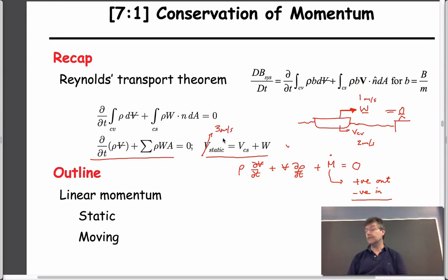So that was the basic tenet. The two important expressions are this mass conservation equation, which is the first thing we wrote just then. Increases in volume are positive, so if the volume gets larger, that's positive, and also increases in density are positive. Those are our sign conventions. We derived it using Reynolds transport theorem, but perhaps that's an overly rigorous way to do it. If we just account for things in some reasonable way, we can end up doing that. In fact, when we did the examples last time, we really just used this single expression. So it's worthwhile knowing.